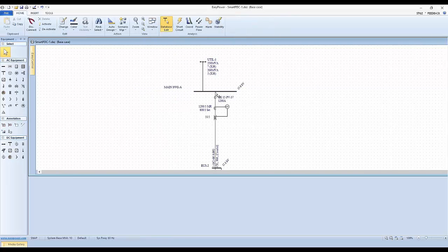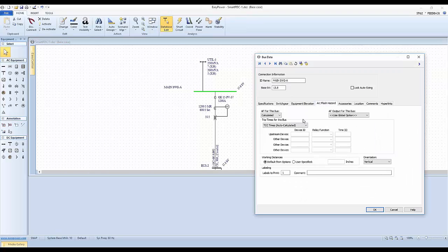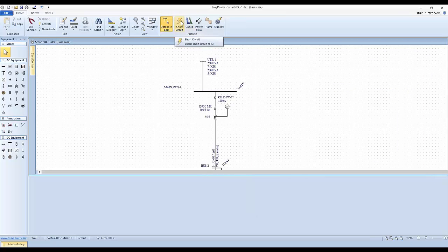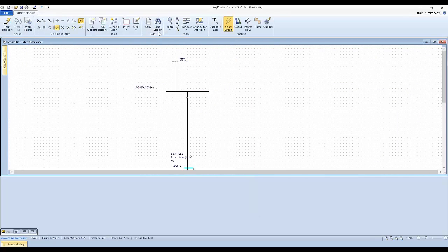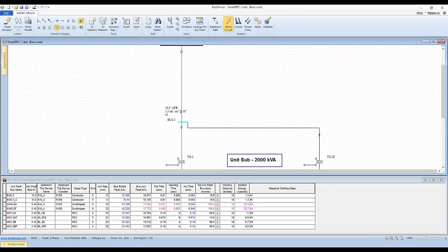Likewise, if we go back to the same local setting and go under arc flash, we may just want to exclude it because nobody ever has to access this gear, in which case when we go back and do a short circuit focus, fault the bus, arrange for arc flash, now our main switchgear A doesn't show up on the listing at all. Okay, now what we've done for each of these is set up our relay, bus 2.